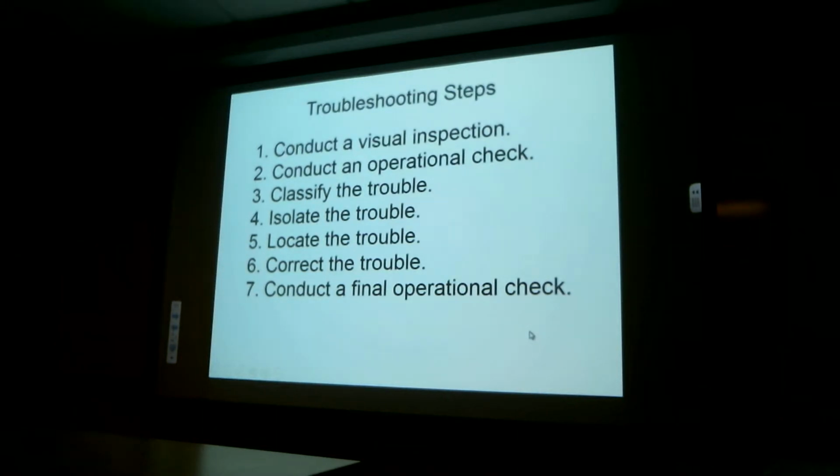An operational check: you don't know exactly what's wrong, so you're going to have to figure out what's going on. This is where it's important to know what normal is for a hydraulic system. If you have no indication of what normal is, how can you ever figure out what's wrong? For example, when you flip a switch on or position a control on an aircraft, what is supposed to happen? So again, an operational check in order to verify what's wrong. But you have to know what normal is before you can even begin. Otherwise, you have no idea what the problem might be.